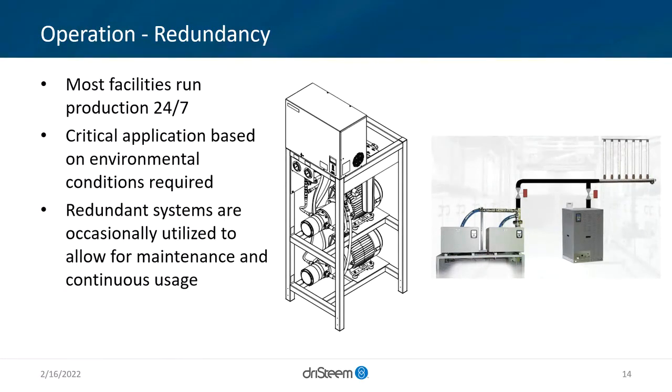So I talked about the example of high pressure atomization for a bulk majority of the load, and then a trim humidifier for that tight control with a resistive unit. This is 2 isothermal, where the GTS, gas to steam, will give the high load, and then that tweaking of the load would be by the electric resistive.